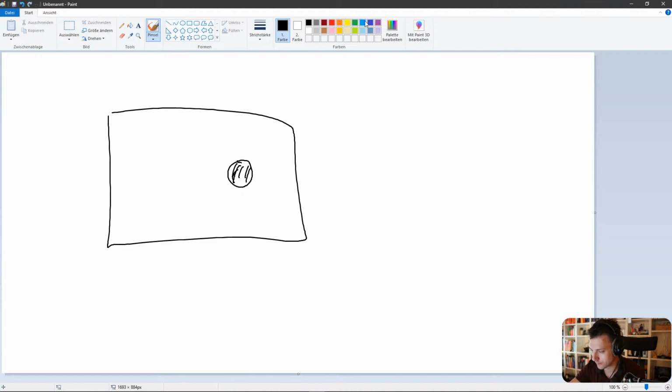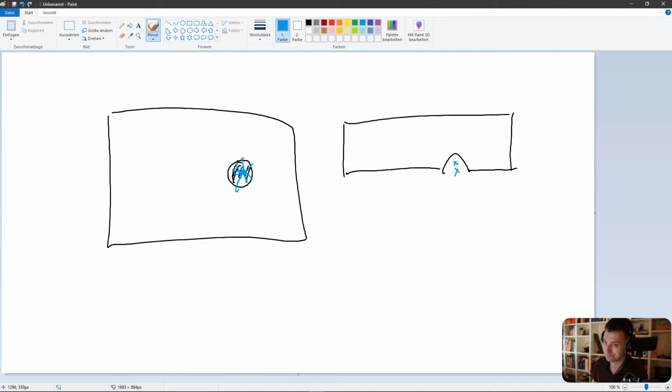And you would like to do a multiple point constraint here and have it perfectly in the center, and then you have your spider all the way around to all of the nodes, right? If you do this on a symmetry model, should the master point then still be at the center? Or should it be at the center of the new surface?